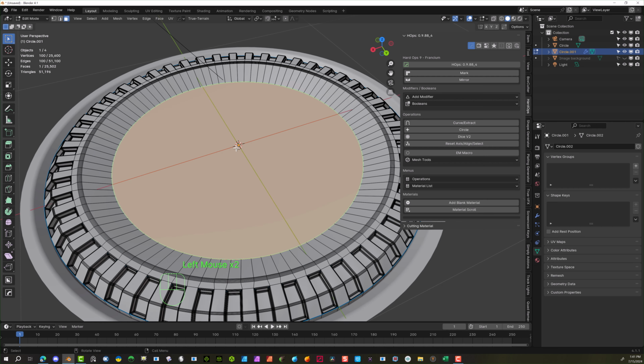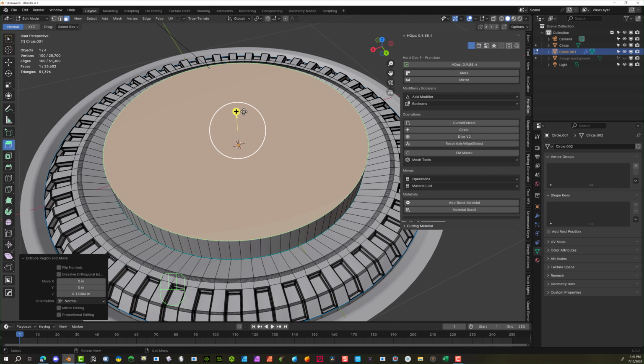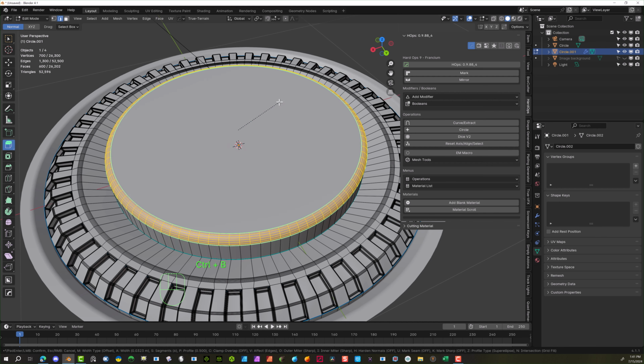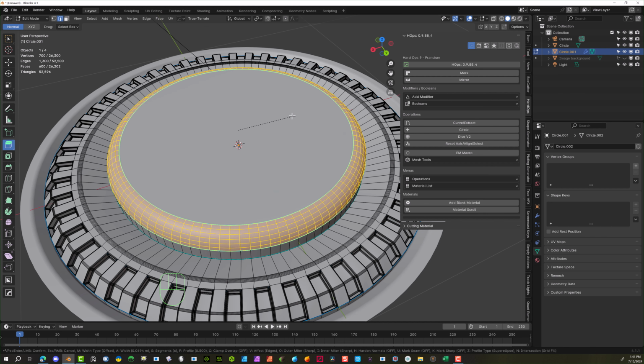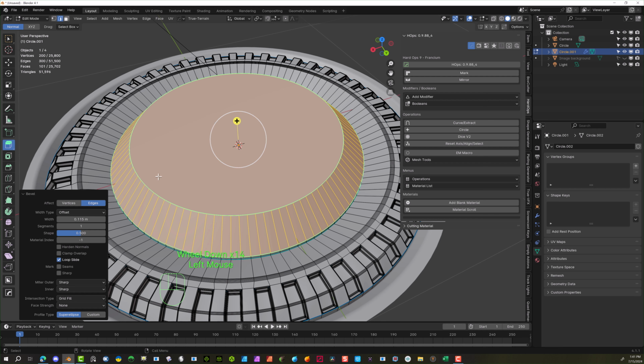Okay, so select this face here. And again, we're going to hit the Extrude key here, and we're going to bring this upward, so we can also hit the E key. Alright, so about right there looks good. And then the next step would be to adjust this. So I'm going to hit the Control B again, and I'm going to bring this out. Again, just use your roll on your mouse. I'm going to make this a chamfer, beginning of all this.